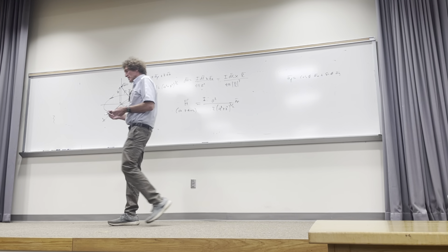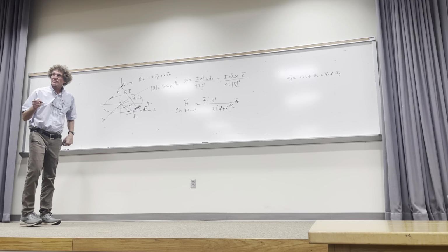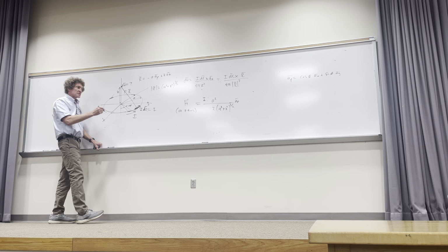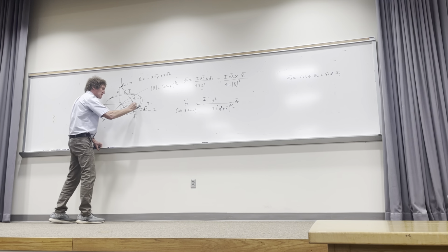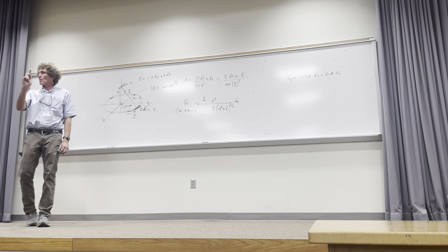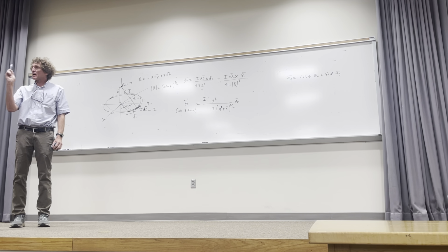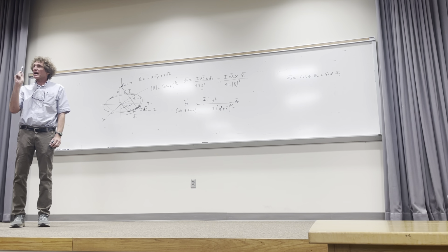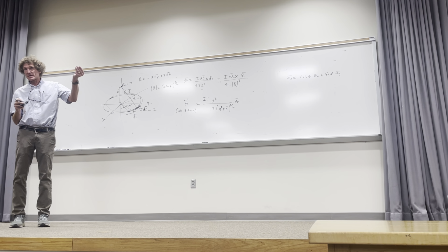I have a question for you. This is just something to see if you're thinking. If that's what it is for one loop, what happens if I put 2 loops on top of each other? In other words, if I have some wire and I wind one wire right on top of the other, but they're shellac or insulated, what do you think is going to happen to that H field? It would double. 3. Triple. As a matter of fact, if they're tightly wound, the more windings just do one thing. They effectively increase the current, right? Flowing, that's the only thing they do. That's basically the thing with a solenoid.